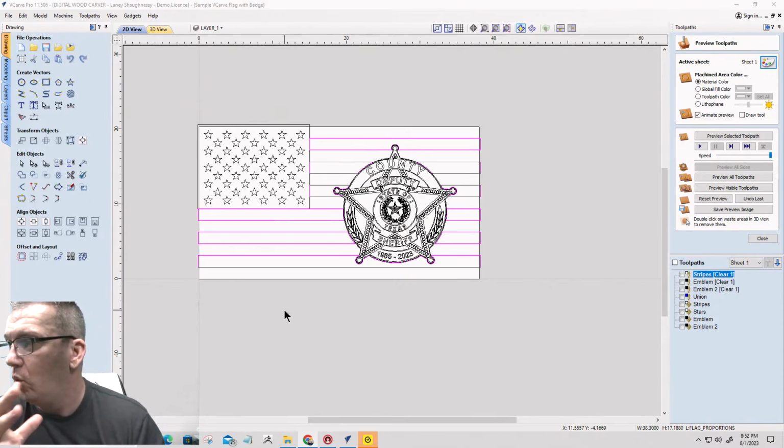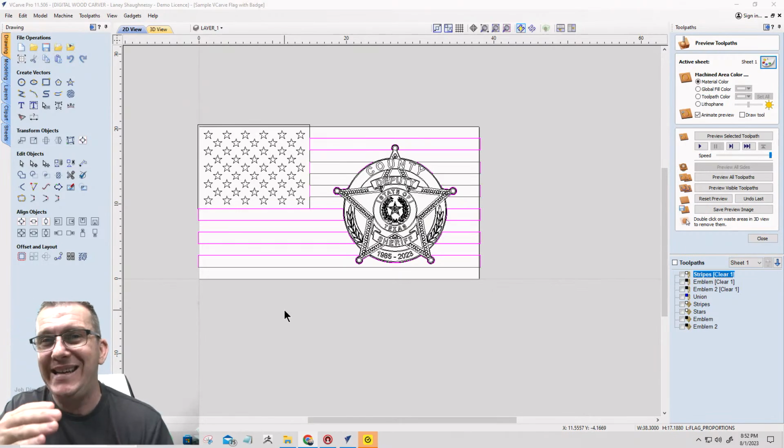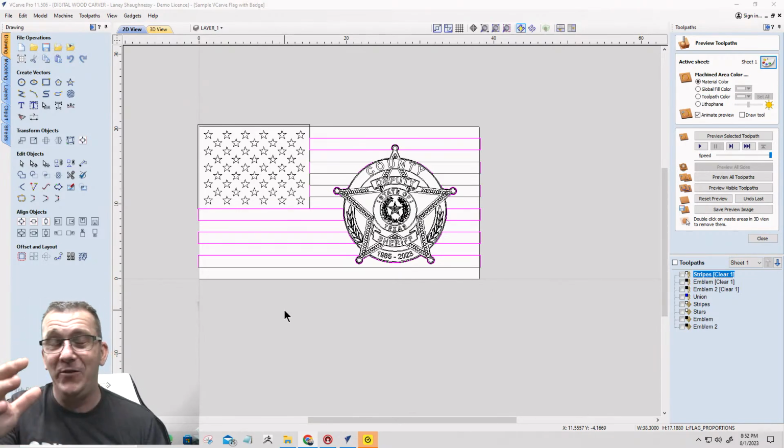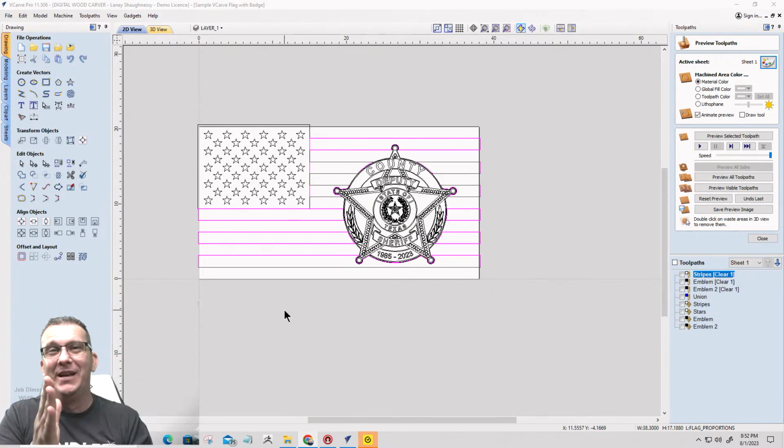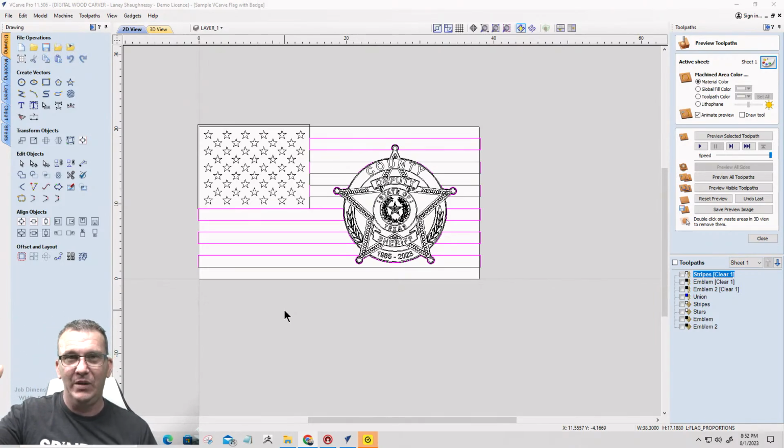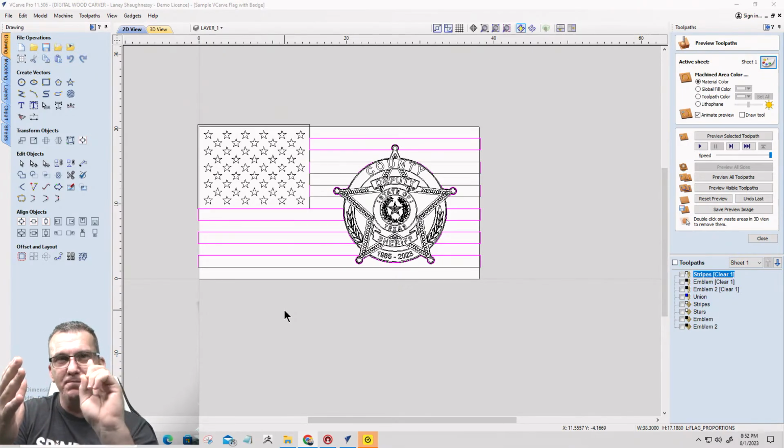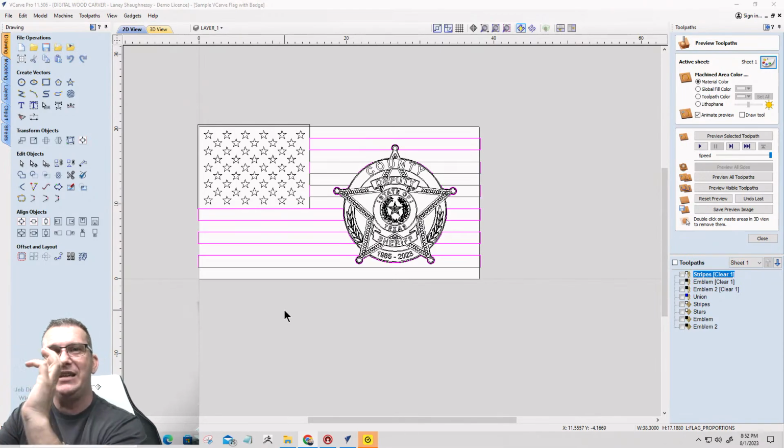Now, if you're going to be on any side of the spectrum, that's the side you want to be on, where the bit is whining, because you just have to go faster and turn that RPM down, spin that bit a little slower. Not too slow, but slow enough that it can take some meat, while moving fast enough that it's taking good chips. We want chips flying out, not dust.